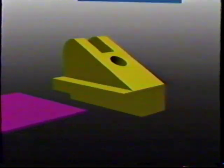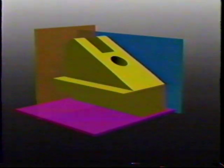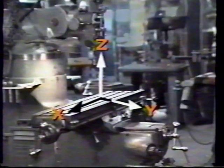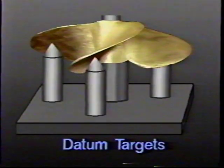As many as 3 datums may be established to accurately define all the features on a part. Together, they form the datum reference frame, which corresponds to the planes formed by the X, Y, Z axes on many machines. For parts with irregular shapes, datums are established by datum targets. Datum targets represent places of contact between the datum feature and the inspection equipment or machine tooling.